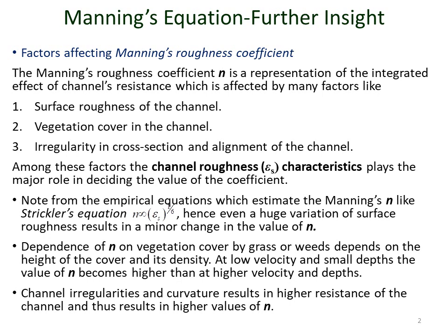The meaning of the statement is, if there's a huge variation in the surface roughness, in the value of epsilon s, there is hardly any major change in the value of the roughness coefficient n, as n is proportional to the surface roughness raised to the power 1/6.